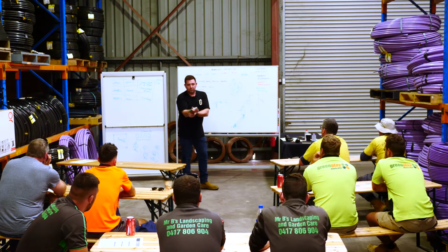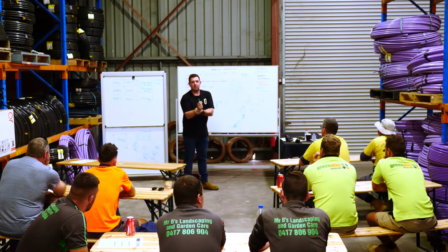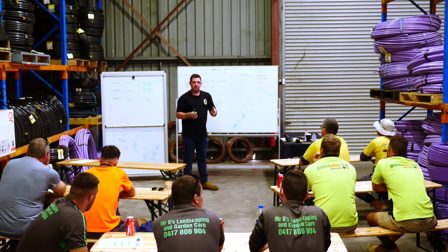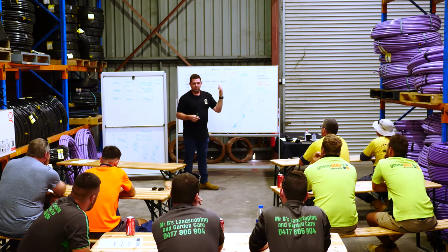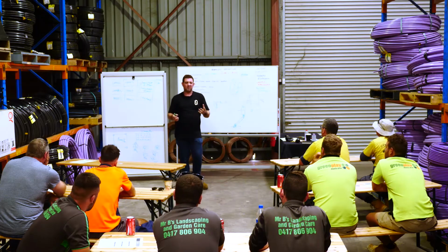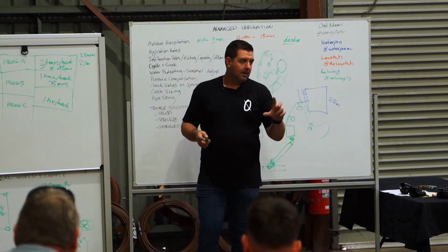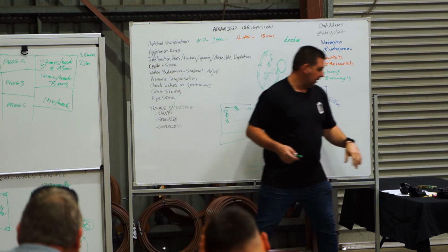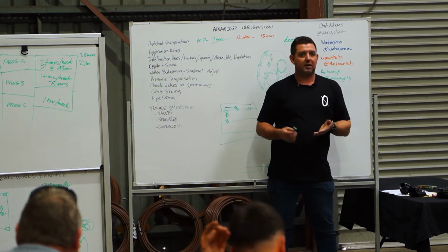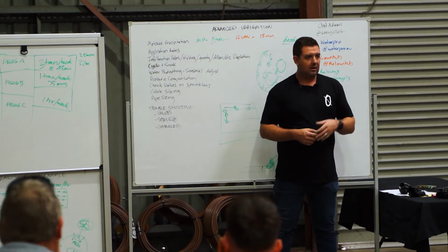One of the big downfalls of decoder systems is they're a massive lightning rod. So when you're installing a decoder system, anything that gets hit on the system with lightning, the whole thing can, not explode, but it'll burn out. A decoder itself, the little toilet roll thingies, they're worth about $100 each. You have one of them hit by lightning, you're getting a new decoder.